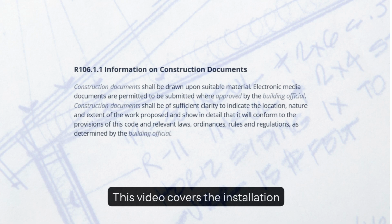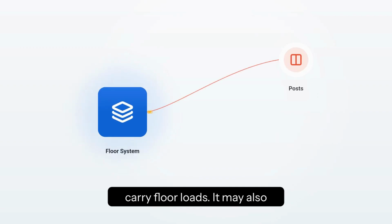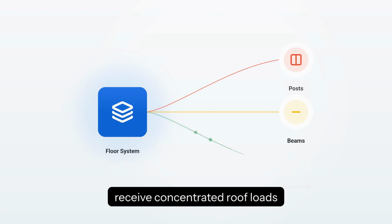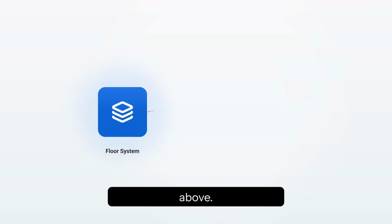This video covers the installation of stick frame roofs over engineered floor systems, according to IRC Section 106.1. Plans must clearly demonstrate code compliance, although this isn't always followed in some regions. The floor system with unknown stick framing above does not just carry floor loads. It may also receive concentrated roof loads through posts, beams, headers, or rafters through framed walls above.